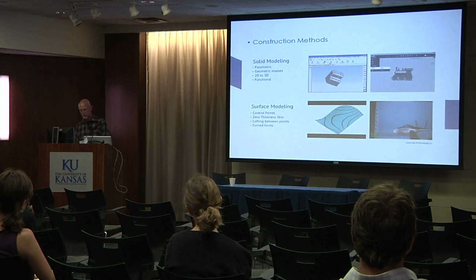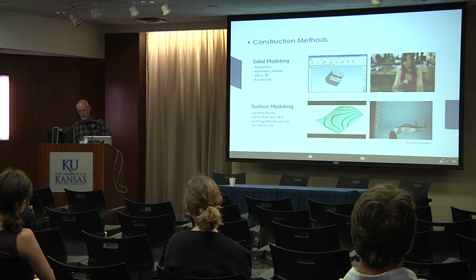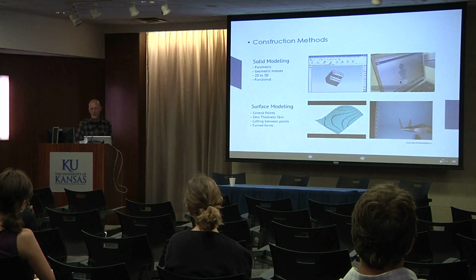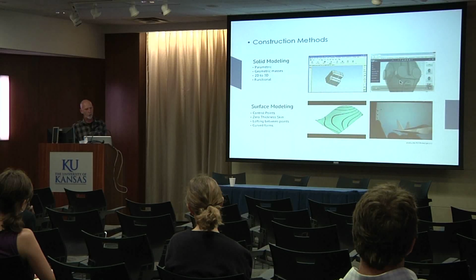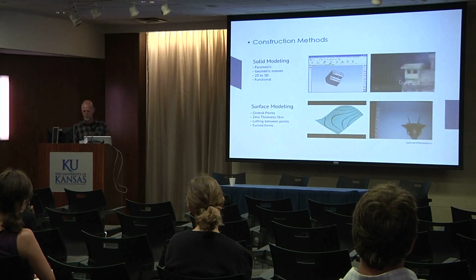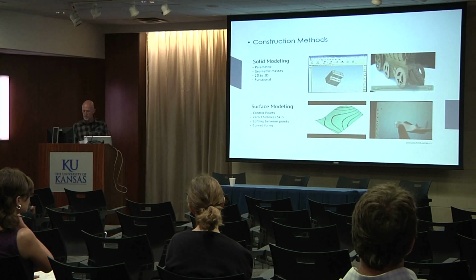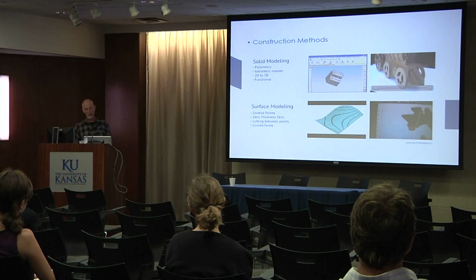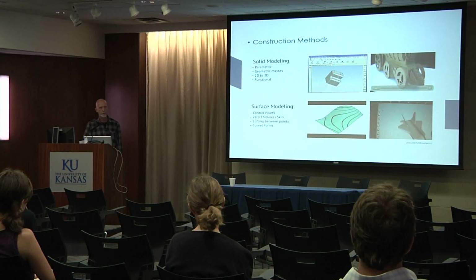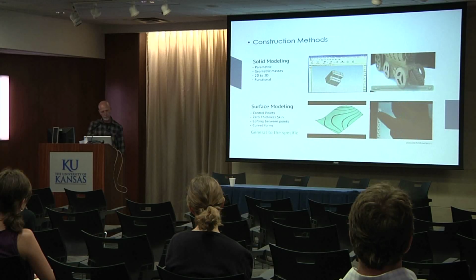This is more evident in contrast. 123D Design, so at the top here, does not allow for push-pull deformation, while dimensioning is not fully parametric on the iPad. The software follows the constructional logic of solid modeling. Forms are built by selecting and extruding surfaces. As with 123D Sculpt, the user can select from a menu of primitives which can be positioned but not deformed. The workflow here, however, is from the specific to the general. So these two methods are working in opposition to each other.